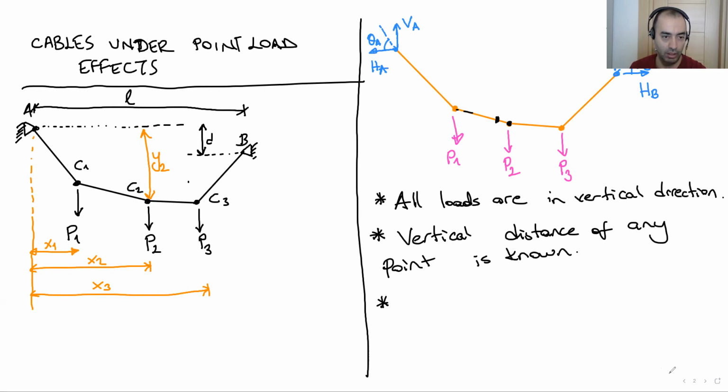This is interesting for us because if you remember our beams, at the end of the day, we generally have 3 support reactions, and at the end of the day, we have 3 equilibrium equations: total x, total y, and total moment is 0. So 3 unknowns, 3 equations. It's easy to solve. That's okay. There is no problem.